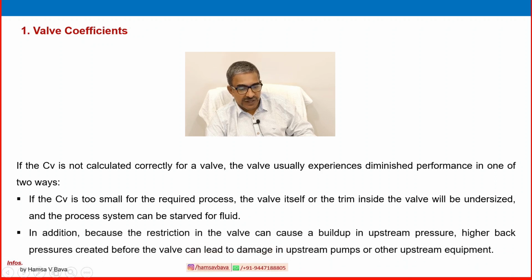In addition, because the restriction in the valve can cause a buildup in upstream pressure, the higher back pressure created before the valve can lead to damage in upstream pumps or other equipment. So the CV calculation, or a suitable CV for the application, will affect the performance in each area.